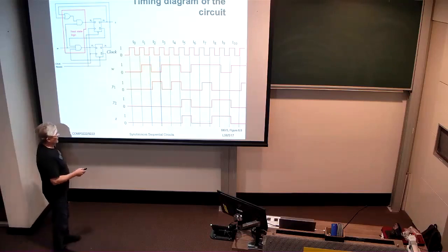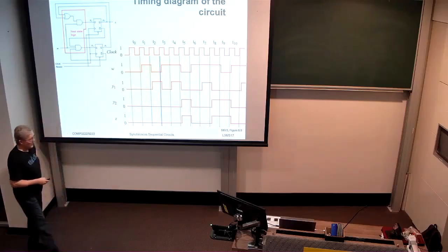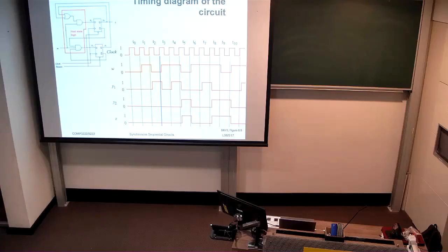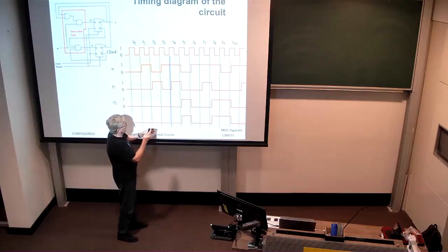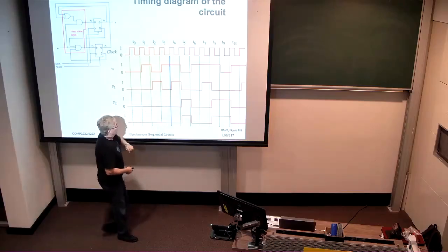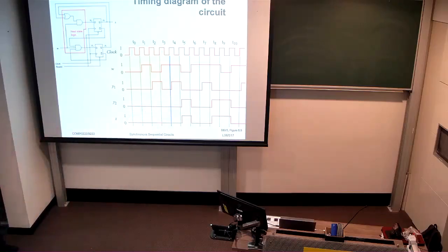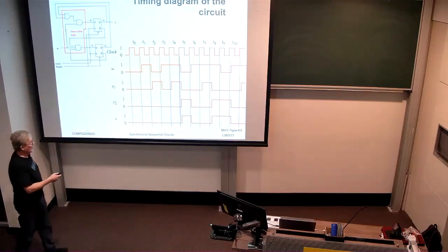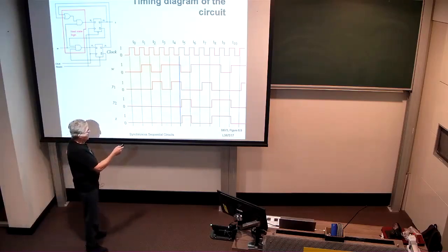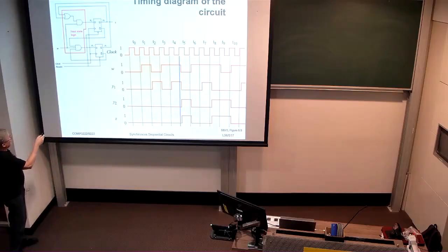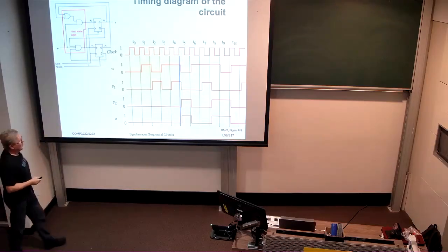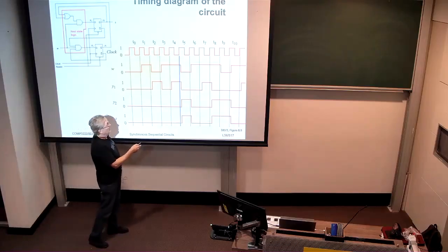On the next positive clock edge, however, W is 0, and therefore the state of the lower flip-flop is changed again to become a 0. On the subsequent rising clock edge at the beginning of period T4, W is 1, therefore we'll see on that rising clock edge again the state 0, 1 appearing. In the next clock period we still see W as 1, and given that that coincides with Y1 being 1, due to the logic that we have up here, that's going to drive this upper flip-flop to be 1 and the lower flip-flop back to be 0.